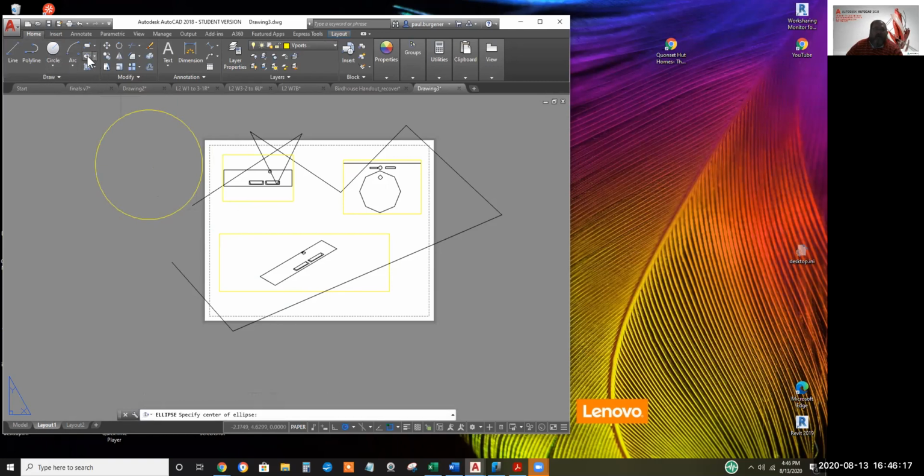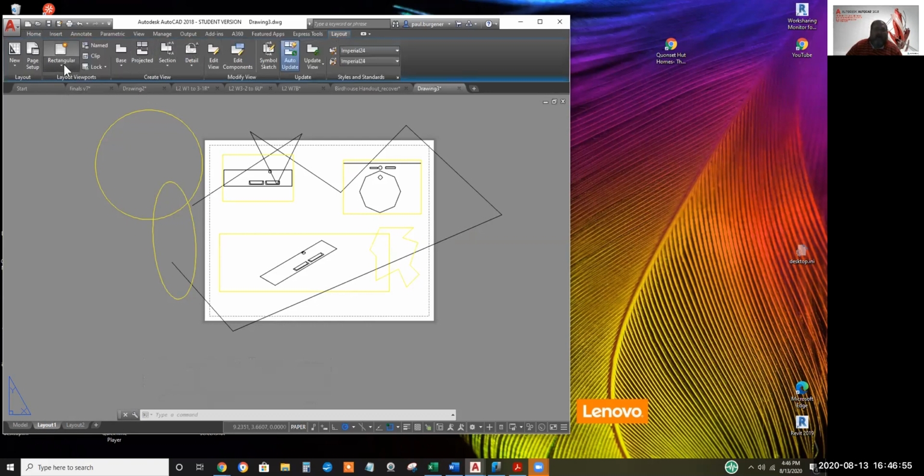I'm not sure. I'm shooting from the hip here, but I think an oval can be a viewport. We'll find out. By far, the most popular way is a polygon or a polyline. And when I do your handouts, I'm all the time making a viewport and wrapping it around C for close, so I get a close-up of the 3D view that I want without the parts next to it in model space. Anyway, I think you have to modify them one at a time.